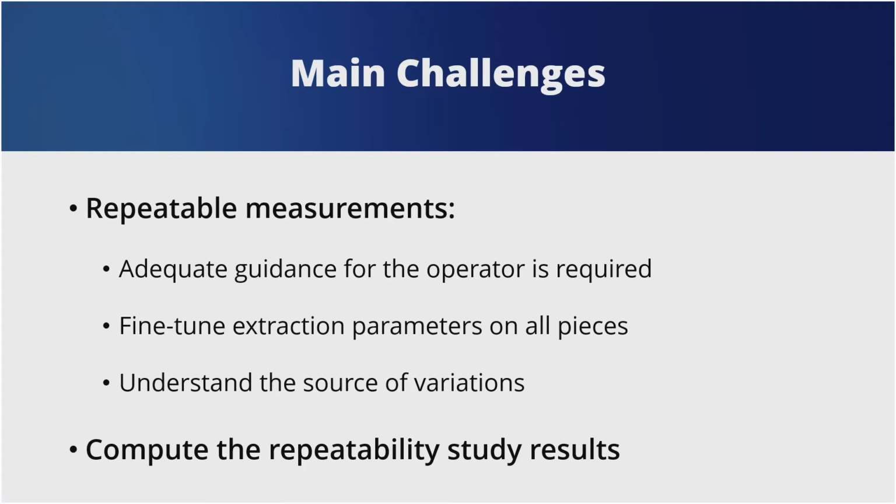Obtaining repeatable measurements is a challenge. Operators without adequate guidance can introduce variations in the measurement process. Extracting measurements on scan data requires fine-tuning measurement parameters to get the optimal results. Variations will be detected, and you need to understand the source of these variations. Finally, performing the repeatability study itself generally requires exporting the measurement results to third-party software to finalize the study.